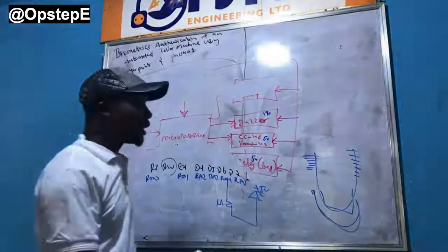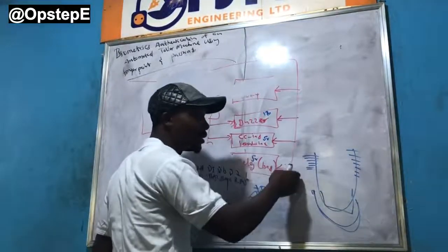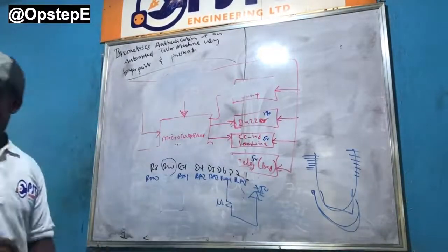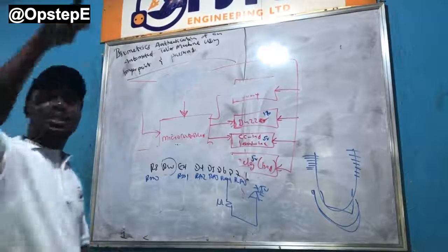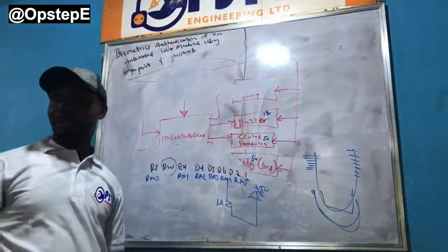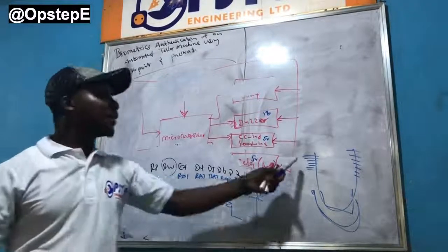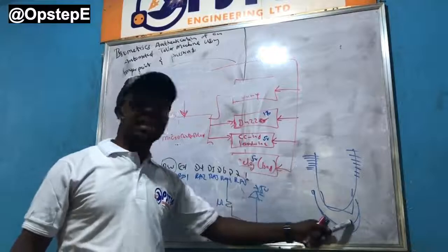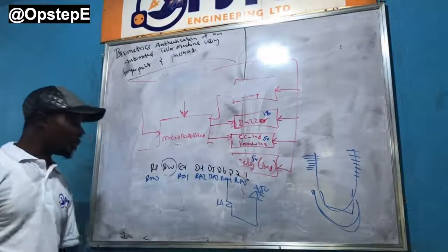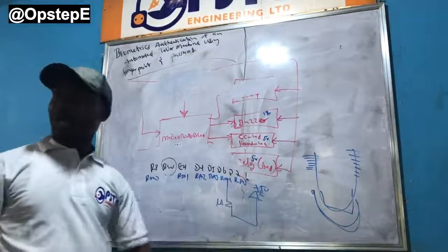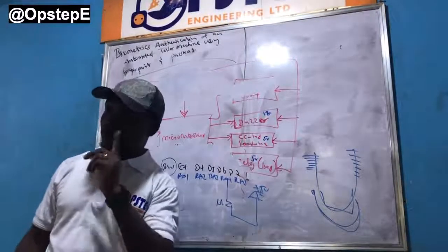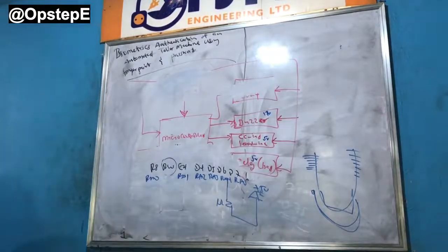So what I have done is I left the keypad here, I left the LCD here, then I brought the fingerprint scanner here, closer to the control. Did you get it? Even at that, I still had about 3 or 4 or 5 jumpers on the board. So now imagine I broke it, and I add 6 here, then the other 6 here. Very rough. You get it? So please, if you are using RA4 as an output, especially RA4, make sure you have a pull-up resistor. So that's that on the LCD.